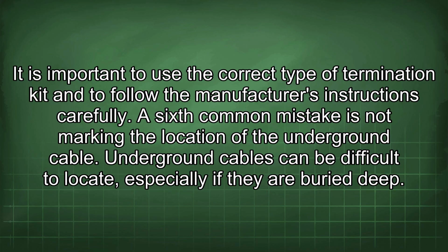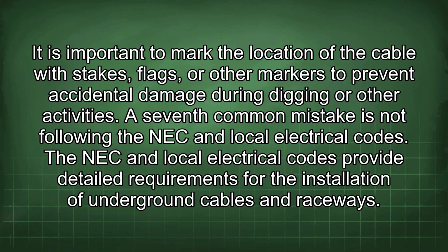It is important to use the correct type of termination kit and to follow the manufacturer's instructions carefully. A sixth common mistake is not marking the location of the underground cable. Underground cables can be difficult to locate, especially if they are buried deep. It is important to mark the location of the cable with stakes, flags, or other markers to prevent accidental damage during digging or other activities.